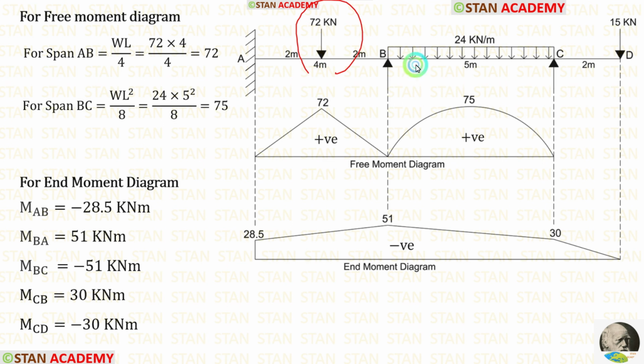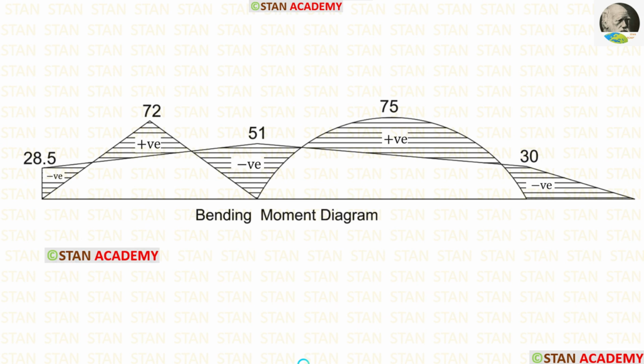Now, using the loads, we can draw the free moment diagram. Using the end moments, we can draw the end moment diagram. Then we have to combine the end moment diagram and the free moment diagram so that we will get the bending moment diagram.